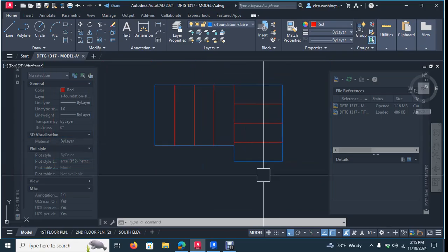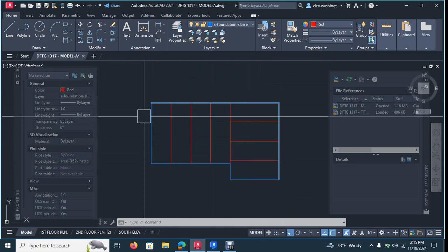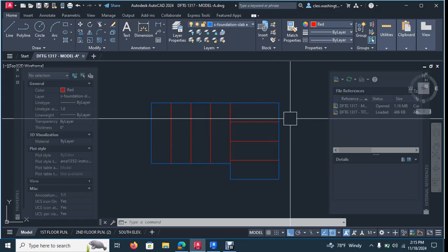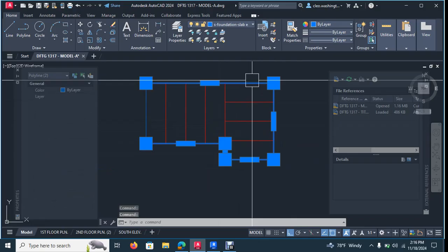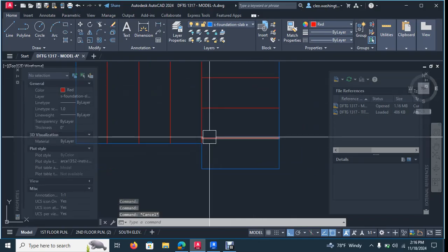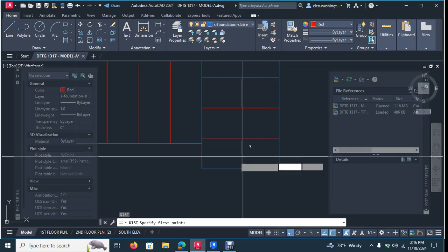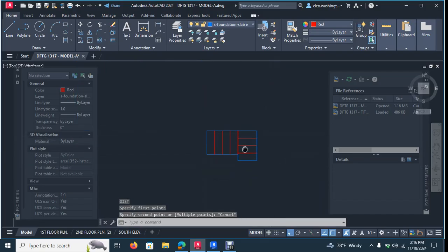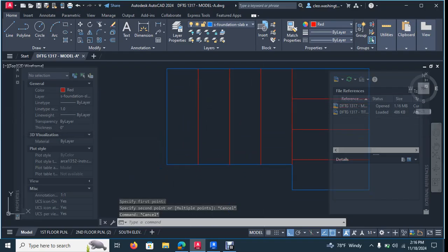Somebody said, why didn't we just do a long one? Because these grade beams can only span so far, and it's always a rule of thumb to keep them spanning the shortest distance. So instead of having one spanning from here to here, you span them this way, which goes from here to here. And typically that is about what? Because I've seen them go long. That's about 23, 24 feet, okay? I've seen them go long, but this is perfect right here, okay?